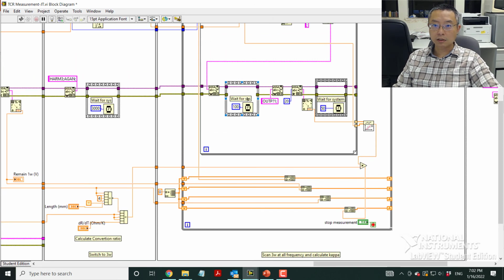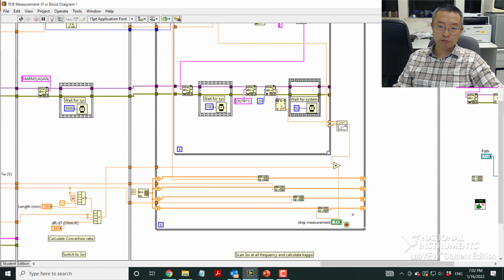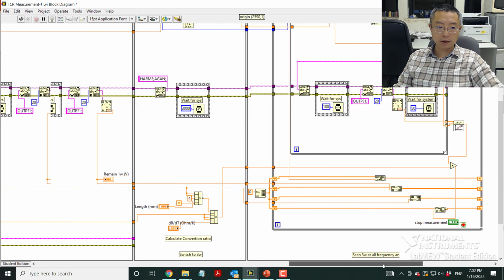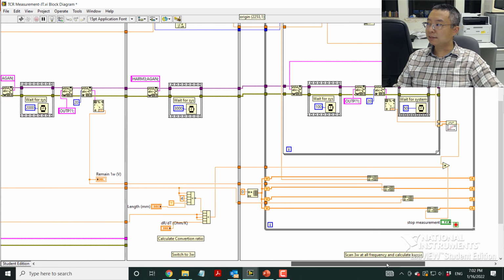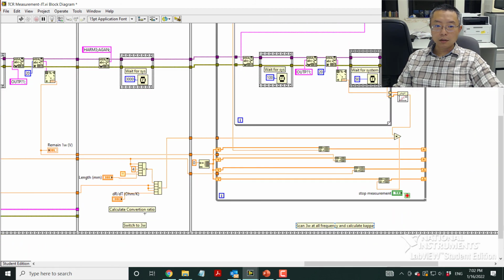But actually, I can put 100 milliseconds or 50 milliseconds. If I have 15 or 20 points, each data measurement probably takes around 2 seconds or so. So in 2 seconds I could get the thermal conductivity. So it's good. I could further increase it, but at this moment I think it's fine. All right. So the next thing is I could just move this a little bit.